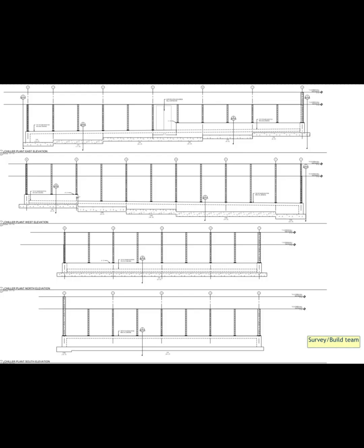The structural notes say a water stop is required midway of the footing centered on the wall. A keyway is required as well. In the coming model, the keyway is off-center. This is an error in the model. The keyway must be centered and run up all the stepped faces.